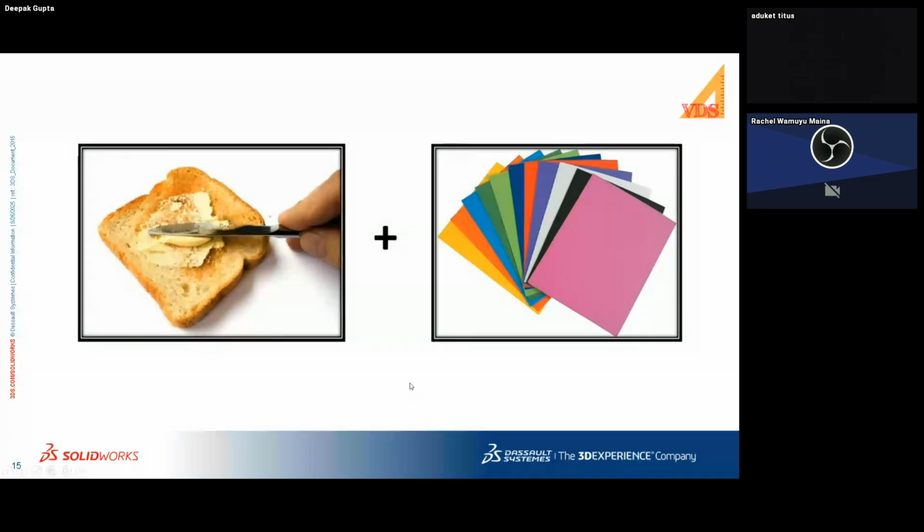Well, when we talk of jog bends, if you look at that particular geometry in the jog bend, assume we have a spherical part or a cylinder, and we want to put a cover on the top of it, but we do not want the cover material to be surrounding it all over. So what we do is we just create four lips on the sides with a bend, which will have a hole, and then that cylinder could have threaded holes, and we can just put in the screw using those holes.